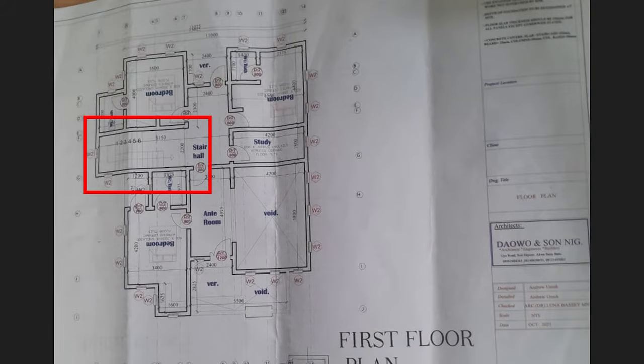But when we created our structural model, we have a beam running across like this, all the way to connect with this one. And in reality, that beam is actually going to appear in the staircase, and it may cause a lot of problems with people crossing the stair. So we're going to have to cut that beam out and allow the beam to stop somewhere here, and then this beam is going to continue this way. Then we can go ahead and create a space for the staircase.